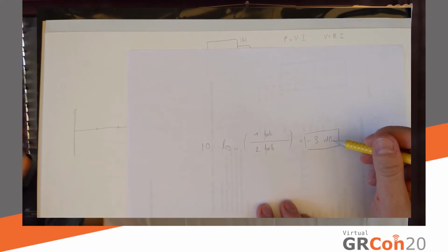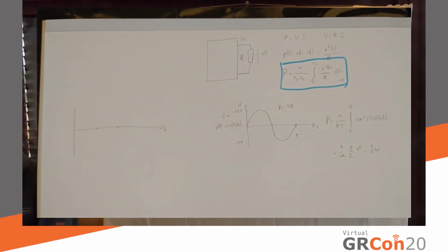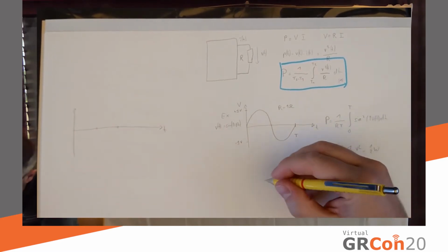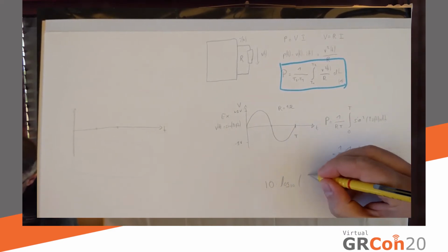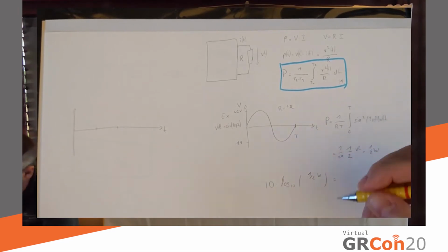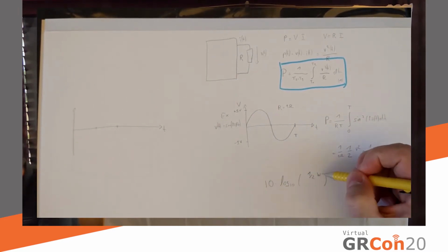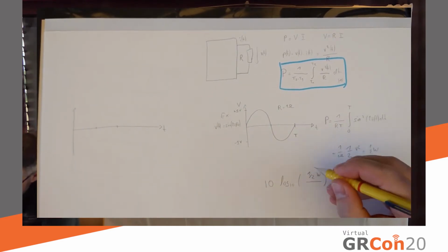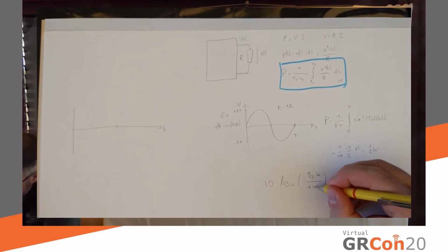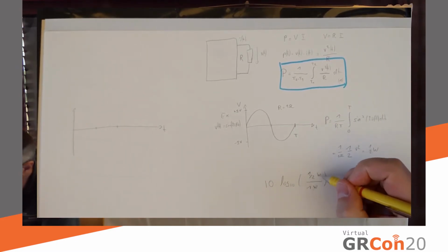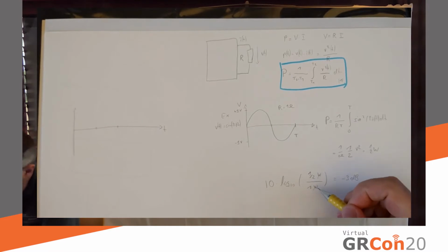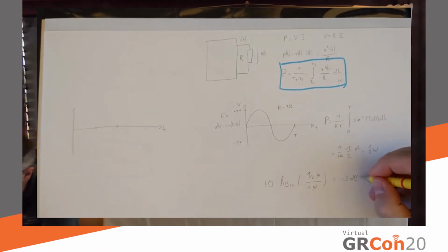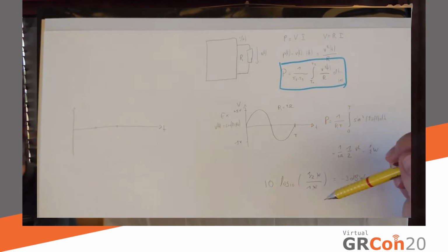However, we like to use these logarithmic units also when we're talking about RF power. So how does that work? Quite simply, let's see what happens if I try and calculate a dB value of that. So 10 times log10 of 1/2 watt equals what? Now I can't really calculate this because I can't take the logarithm of watts, but what I can do is calculate a ratio where my reference value is 1 watt. So the watts cancel out, leaving us again at minus 3 dB. But because I snuck in this watt to actually make the math possible, I have to add it here again just to make sure I knew what I talked about. So minus 3 dBW is the same as 1/2 watt, except in a logarithmic fashion.